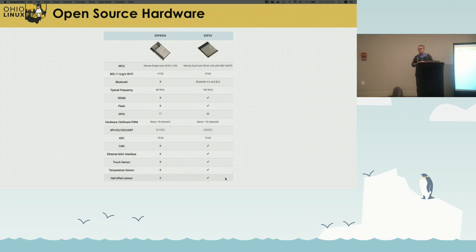And they have a capacitive touch sensor. So we can assign capacitive touch to one of these pins, which is basically mapped to one of the pins on the board. And then we can touch it with a hand, and the board will know that it's being touched. This is useful for things like you could wire it to a door frame. Of course, we're talking about not wiring this board. You build a finished system that is a box that you mount to the wall. You wire it to a door frame, wire it to a desk, and you'll be able to tell if someone has touched that thing and how many times.